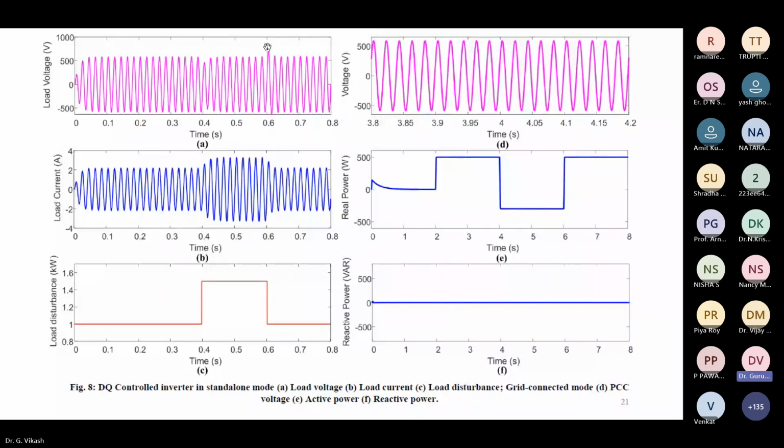And in grid connected mode, we are giving some reference active and reactive powers here. Actually, the D is fixed. The D is not changing because this is the PCC voltage, so it won't affect. But the real and reactive power set points, we have already set.